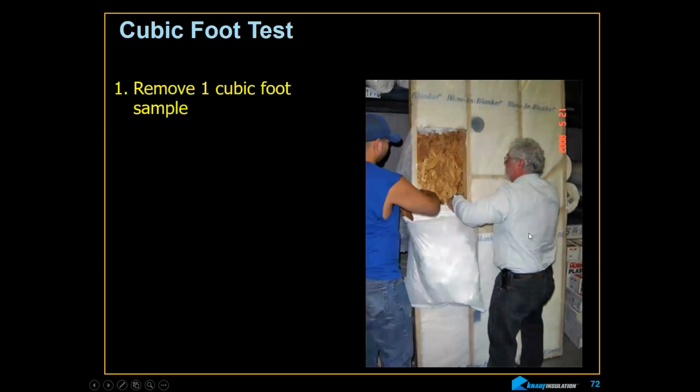If you're filling insulation with a blown-in system, you have to test it for density. You can't just put your hand on it and feel it and visually walk by it and say it's got the right density so that I know that it is the correct R value. Now you can see that this stuff will stay in place. This is hard to pull out. You can actually take the facing material off of it that's only used for installation if you want to, and it will all stay in place. Nobody does it because it's a waste. There's no reason to do that. And sometimes it's a vapor retarder. A lot of different systems you can use.